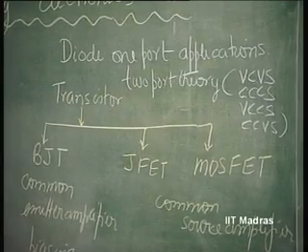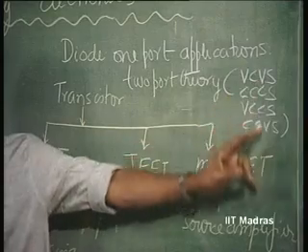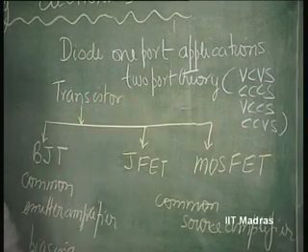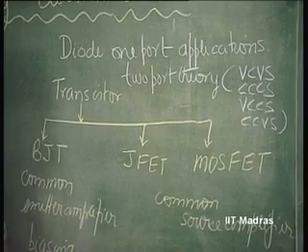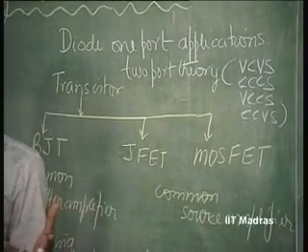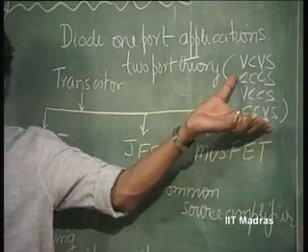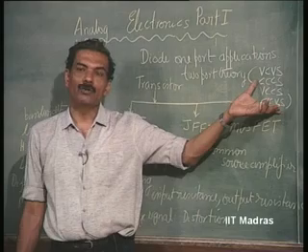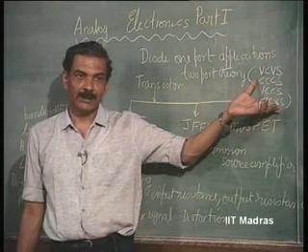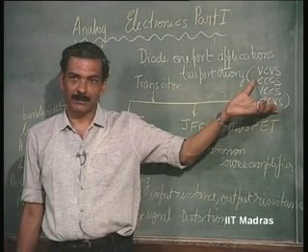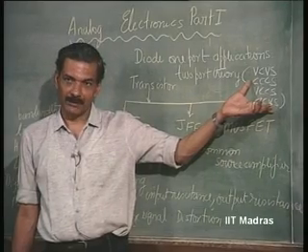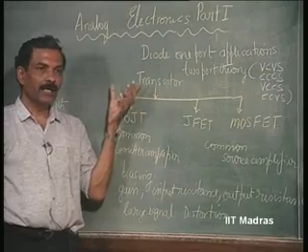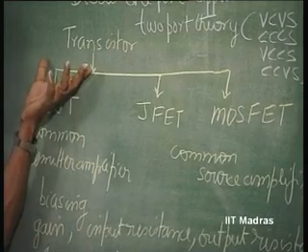Idealized amplifiers are these control sources, with 2-port parameters, which are H, Y, Z and G. We understood how to use these parameters in defining these ideal sources, what the non-idealities are, and how to evaluate the input resistance, output resistance and transfer parameter in these amplifiers. That is 2-port network theory. Then we went over to the actual active device, the 3-terminal device.